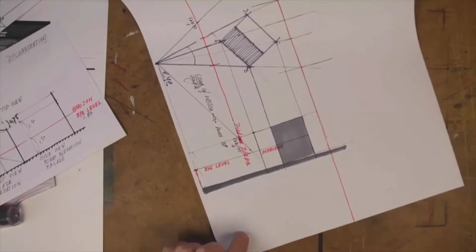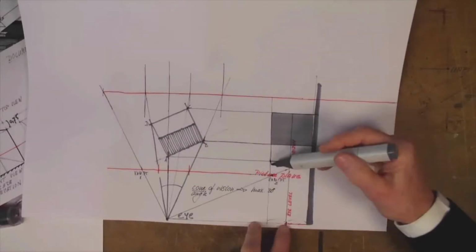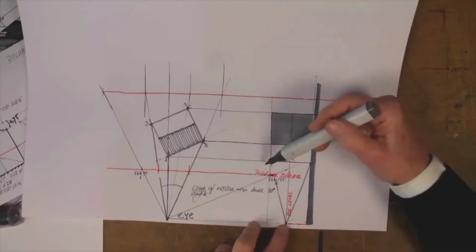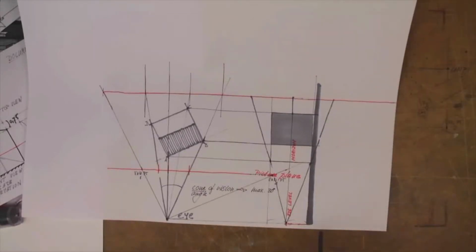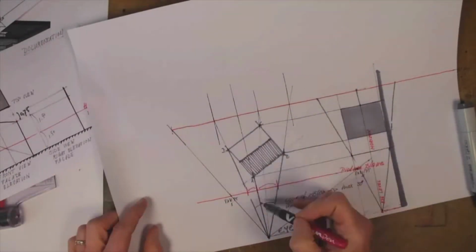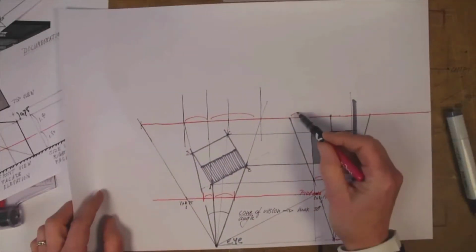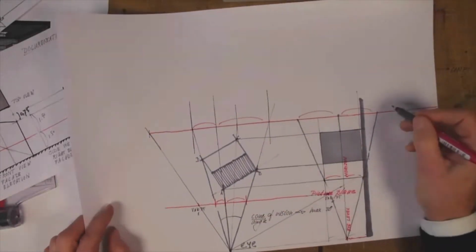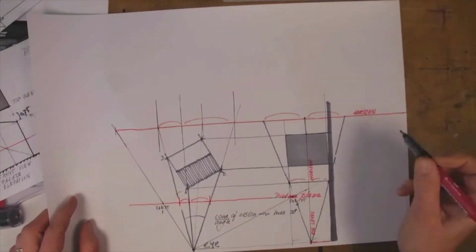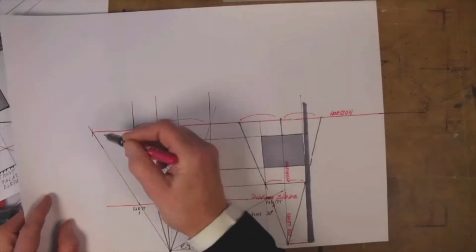The horizontal line starting from my eyes looking straight towards the object is the horizon in the side view. I put the rays from my point of view to the object and extend those lines until I meet the picture plane. The sizes of the height will grow in the same ratio as seen in the top view. Now I can use the line of the picture plane also as being the horizon. The vanishing points are there already.